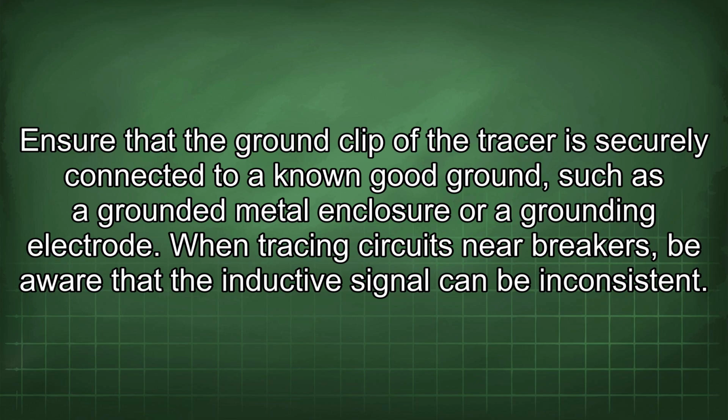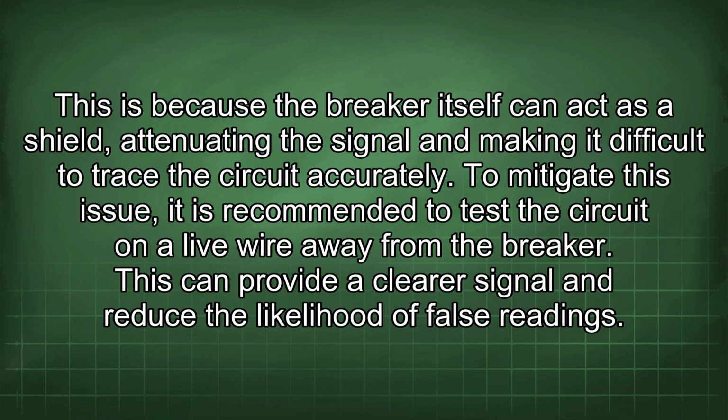When tracing circuits near breakers, be aware that the inductive signal can be inconsistent. This is because the breaker itself can act as a shield, attenuating the signal and making it difficult to trace the circuit accurately. To mitigate this issue, it is recommended to test the circuit on a live wire away from the breaker. This can provide a clearer signal and reduce the likelihood of false readings.